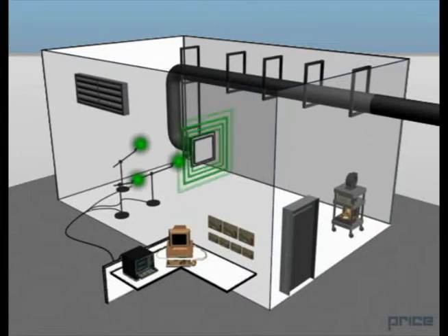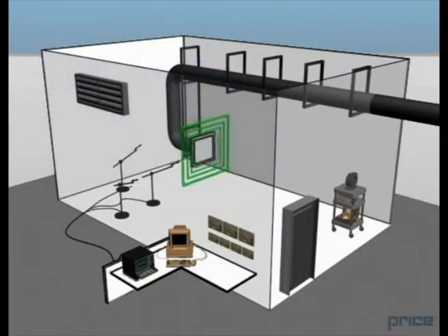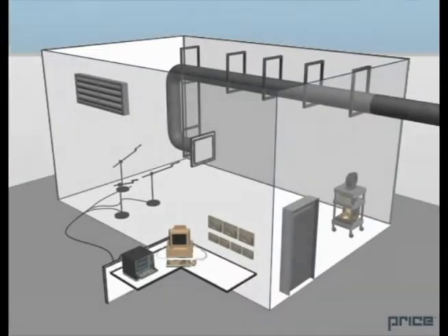These readings are made under carefully controlled circumstances so as to determine the amount of noise produced by the item in the absence of any dampening influences. Sound absorption in the room is minimized by the specially coated walls and concrete construction. Background noise checks and regular calibration ensure that testing is done in a consistent and precise manner. The resulting sound data is published in the Price Air Distribution Catalog in order to help you select the right products for the right environment.